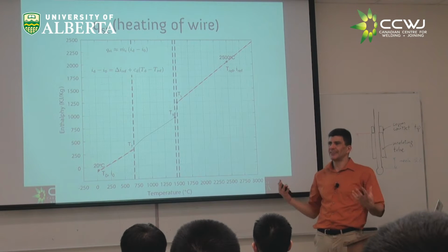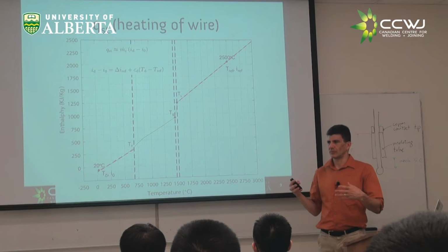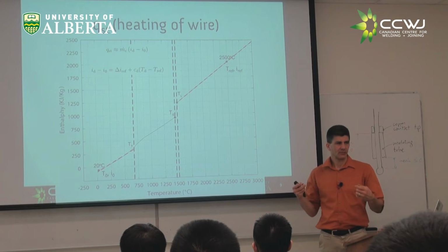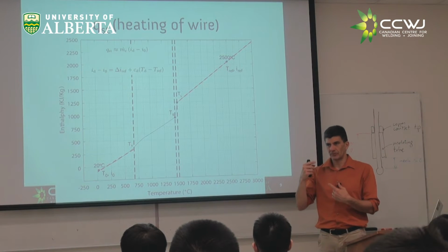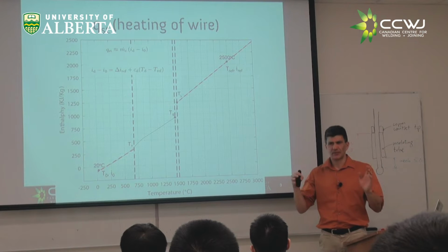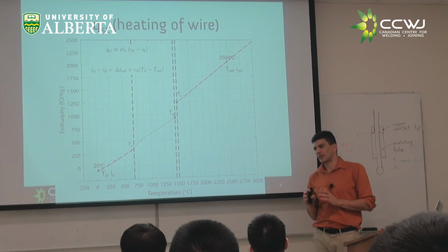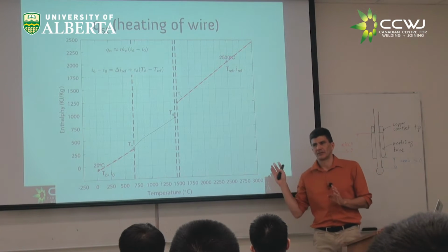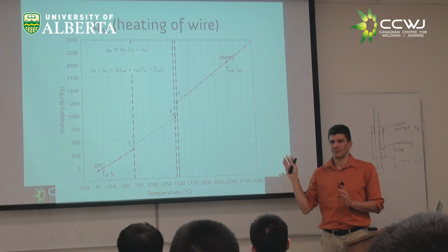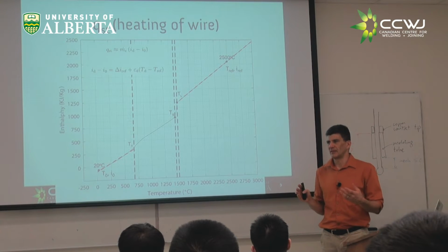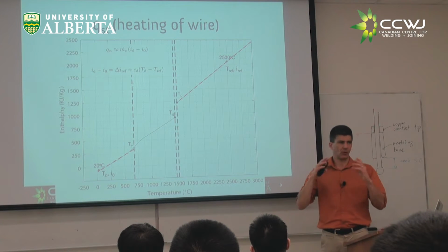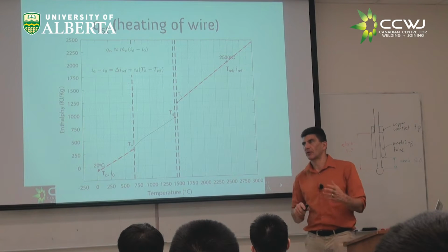What heat comes into the wire from outside the control volume? What would that be? The heat from the fall voltage, right? And from the contact tip, those two. There are more things, but we said let's forget. How much heat gets out of the electrode? Let's call it 0 right now. Evaporation is the largest, and even that in the whole balance is very small. So we're going to forget about it.